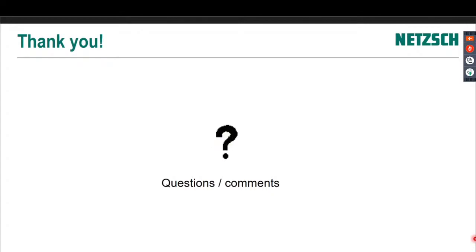So the next question is about recovery tests. Are they always run with dynamic oscillation, or are there situations where static shear would be applied? Yeah, so there's two ways of doing this test. You can do oscillation, shear, oscillation. So you oscillate at the beginning to see the initial modulus, and then shear it a little bit, and then you oscillate at the end. Now that would simulate stop, go, stop, right? That would basically not move and then flowing and then not moving. So if you want to simulate stop, go, stop, then it would be oscillation, shear, oscillation.